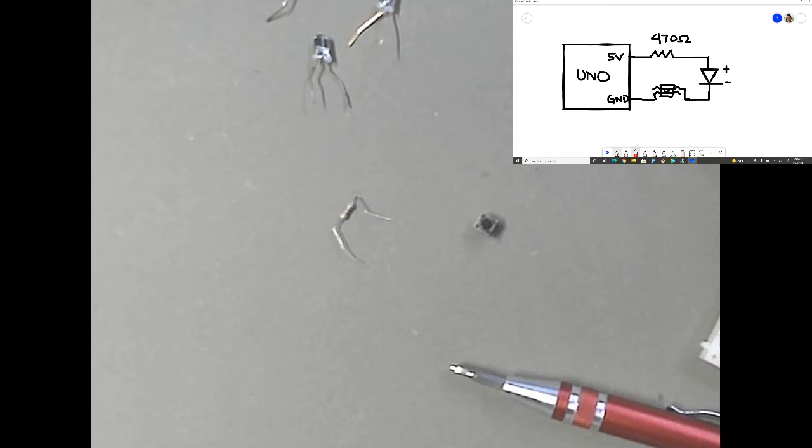So now let's see what happens. If you press the button, though, what happens? The top leg connects to the bottom leg. And remember, only for that moment, as long as you press the button. If the top leg connects to the bottom leg, electricity comes through here, and it goes down that path, goes to GND, and once I do that, the light turns on. And that's it. So let's try that. Okay? Let's go ahead and build this circuit.